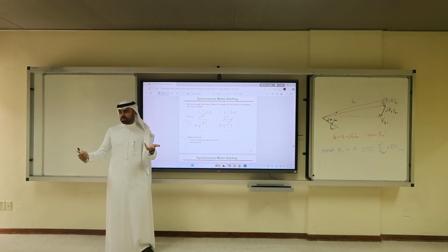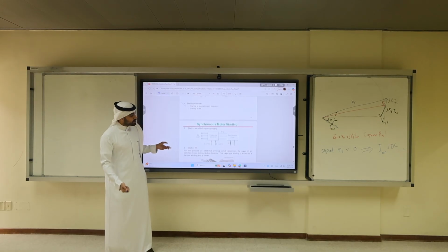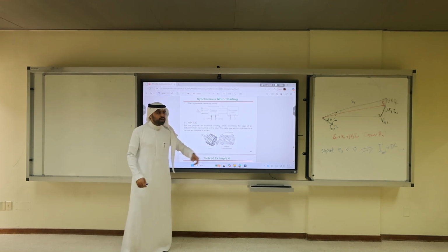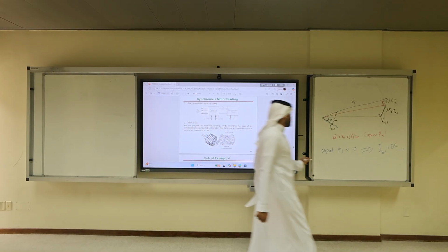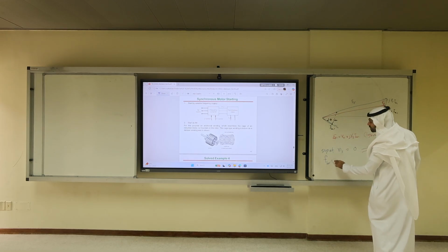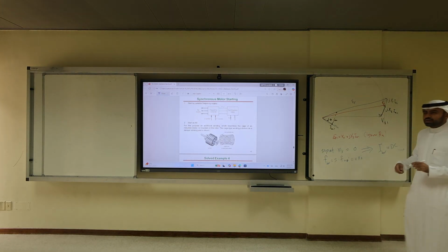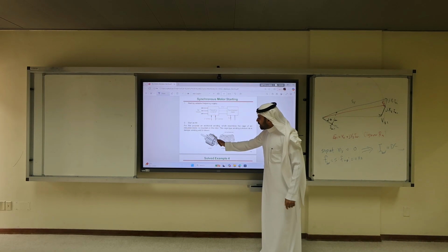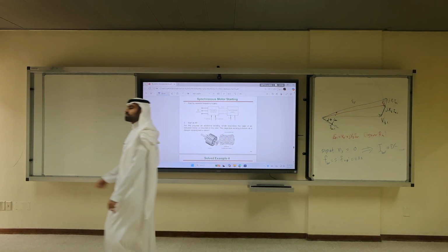So it's your choice. You want to start it, lose some weight, and then during synchronous speed this will be useless. Remember the equation? The frequency of the bar current. Frequency of the bar is the slip times F supply. So it will be 0 hertz. That's why it's DC. There might be some current, so you might have minor losses. But this bar that is excited using DC would still rotate at synchronous. Get it?